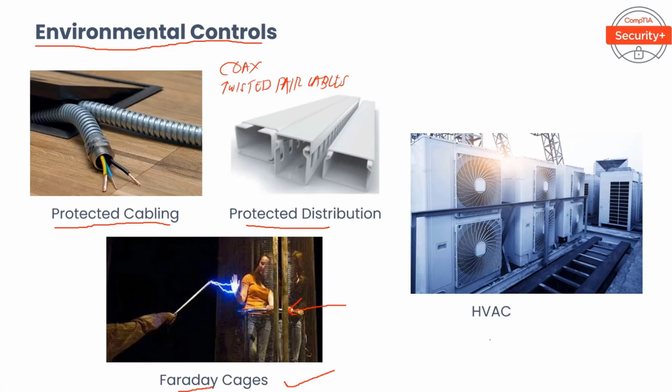And the last part is HVAC, which stands for heating, ventilation, and air conditioning. When doing facilities planning, you need to take into consideration the cooling requirements of computer data centers and server rooms. The amount of heat generated by some of this equipment is extremely variable. Depending on the size of the space and the age and type of equipment the room contains, energy consumption typically ranges from 20 to 100 watts per square foot.